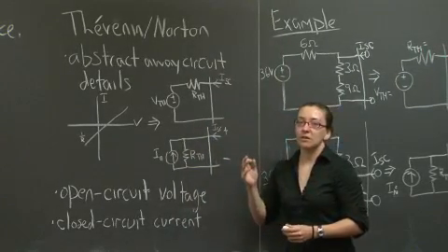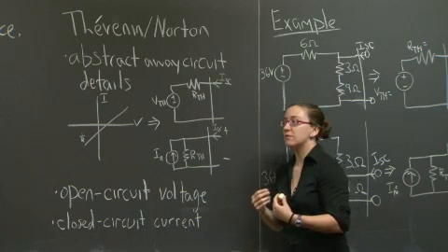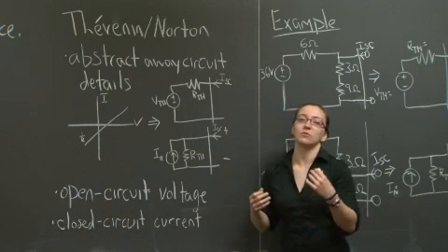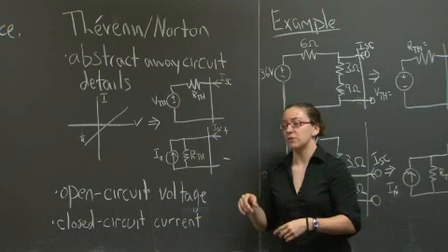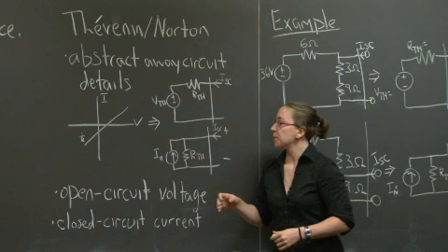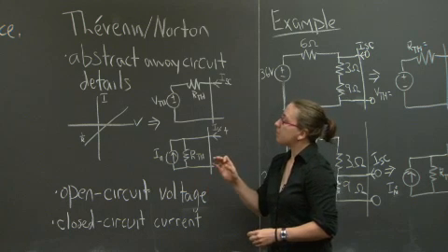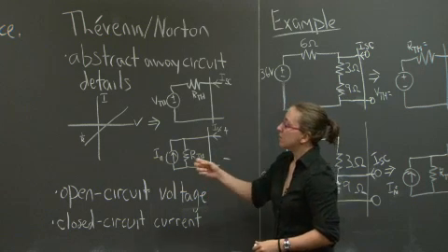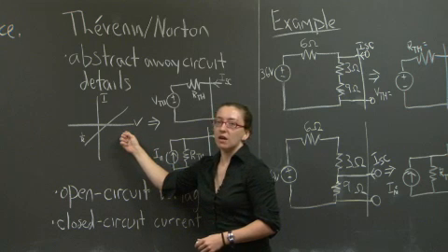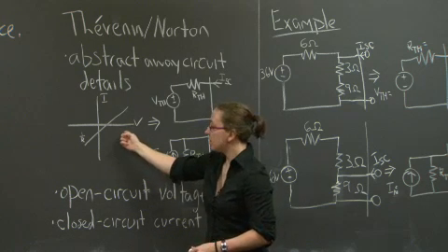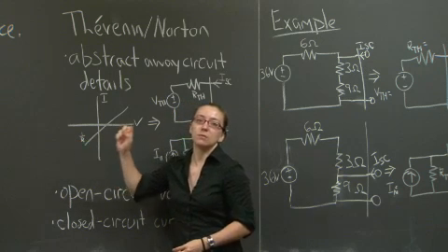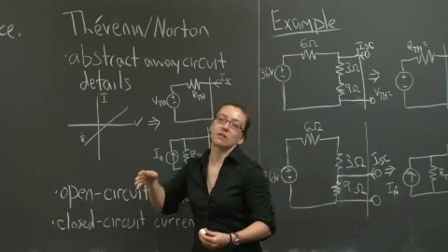Thevenin and Norton equivalence is an important concept in that you may have a very complicated circuit and you don't really want to talk about the entire complicated circuit. You just want to sample the voltage drop or current in a very particular location. Because we're dealing with LTI systems, we can actually express that particular sample as its relationship between I and V and possibly whatever resistive component is associated with the voltage drop across that sample.